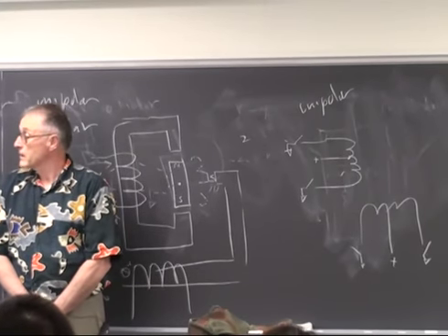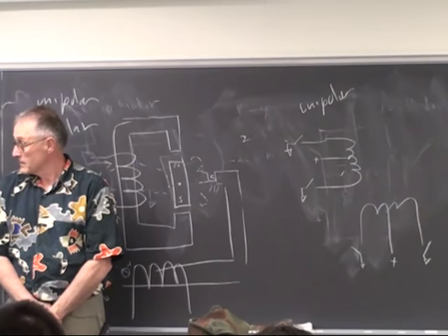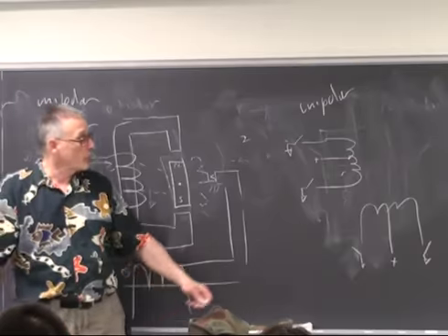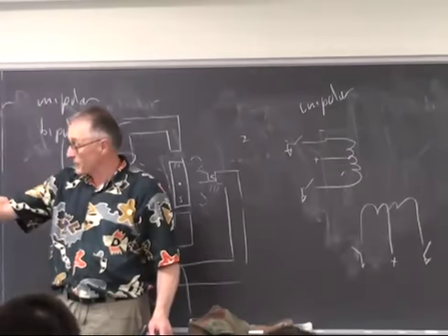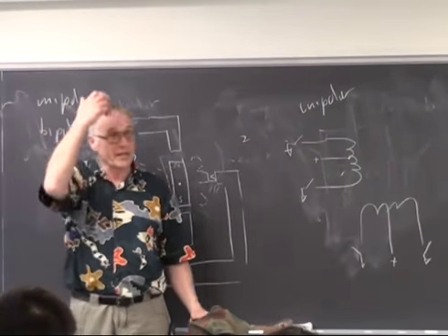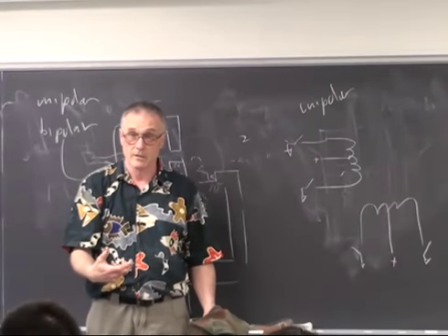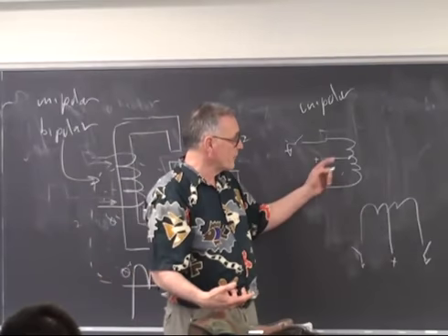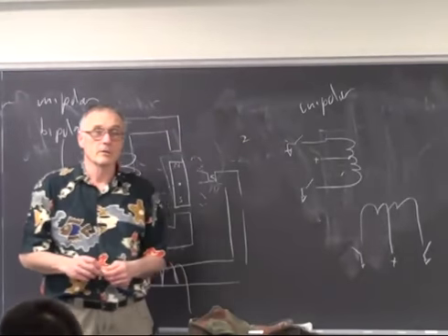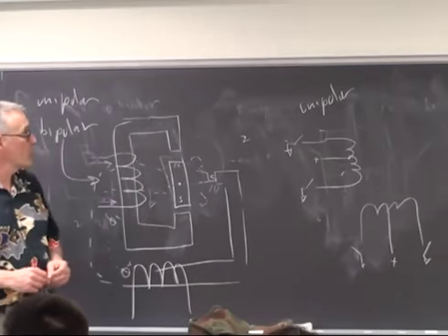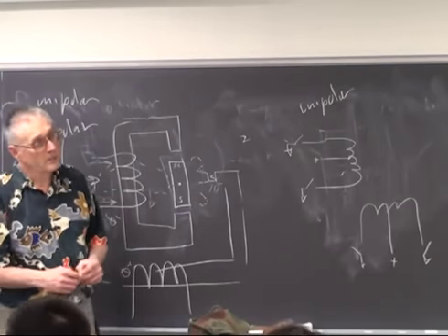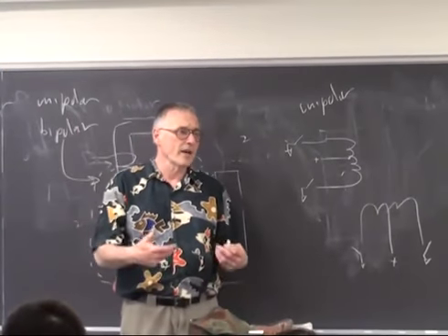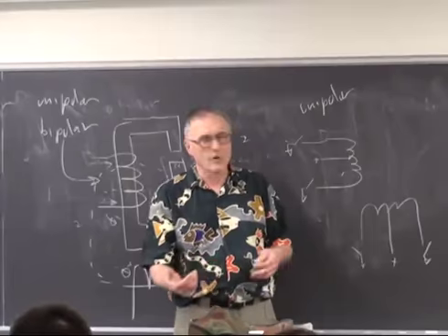Size, yes. Exactly, you have to double the coil size for a given torque. Quite right. Or put it differently, at any given time you're only using half of the coil. And so you only get half the torque for the same coil mass. Nonetheless, you see quite a few unipolar motors around, because if you don't need very much torque and the drive circuitry is cost sensitive, then you go this way.